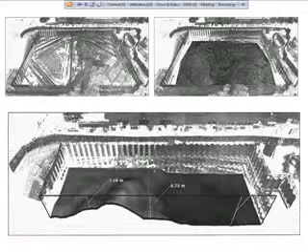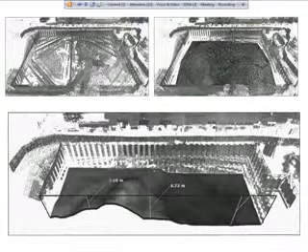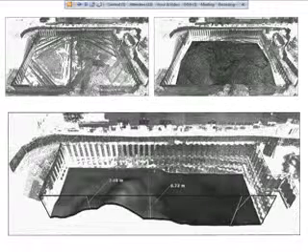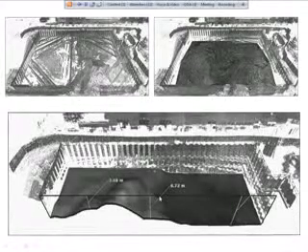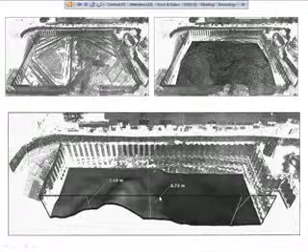This is another snapshot of the same process too, and this is kind of what I was talking about on the bottom. You can see at the top here we have two open excavations. One on the left is an actual picture, and then the right is with the picture, but it has the scanned information overlaid. Utilizing the section tool in Navisworks, we can quickly determine, have they achieved their goal? Where they managed to dig down deep enough?